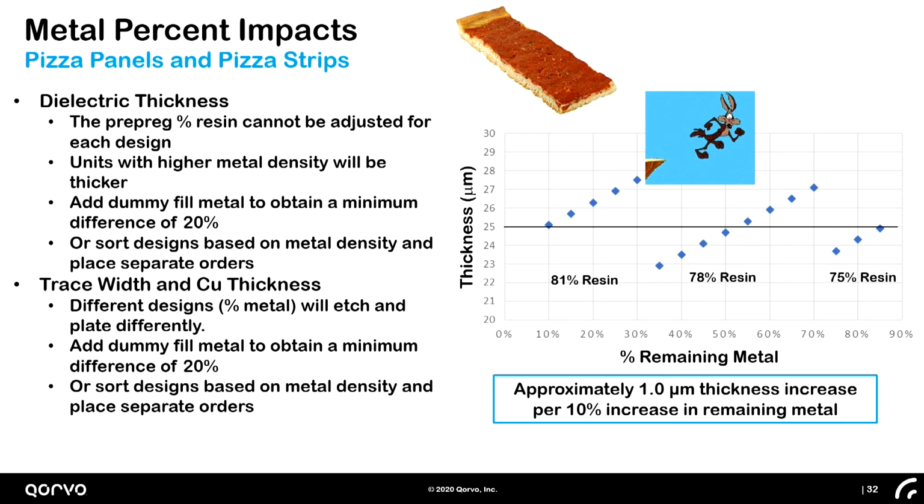A lot of the transmission lines are very sparse, right? So there's not a lot around them. There's other cases where people try to fix the metal percentage by putting fill patterns in, but they're running a transmission line over one fill pattern, and then the next transmission line over, there's no fill underneath it. So you're not really characterizing what you think you are, because they're just different metal blocks underneath. So that's a problem. And dummy fill is needed because on opposing layers, if the percentages are different, it'll warp, right? That makes it hard to put the pieces down on it. That's one of the problems that we've got with that.